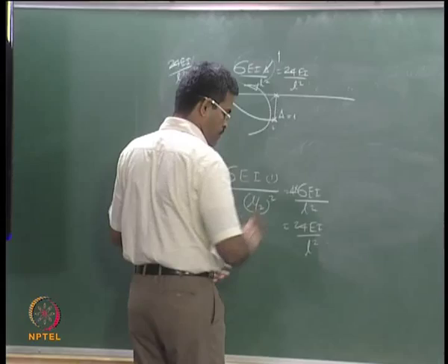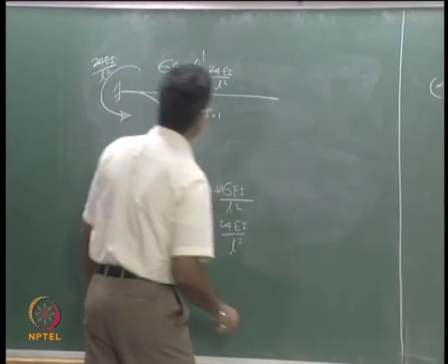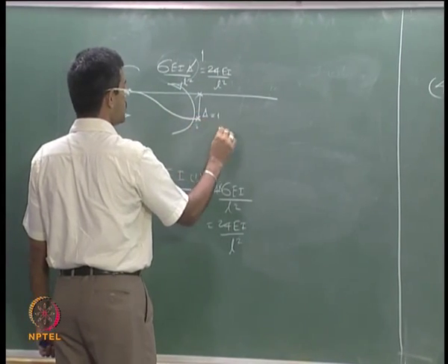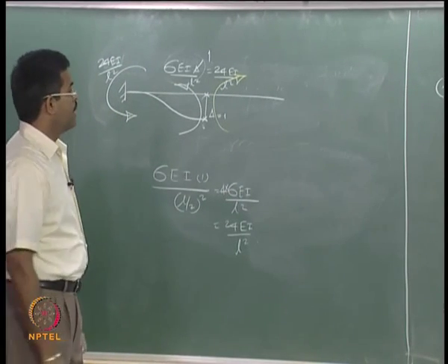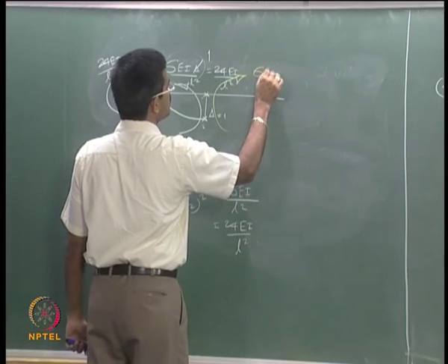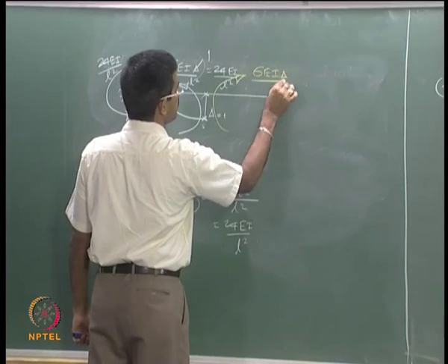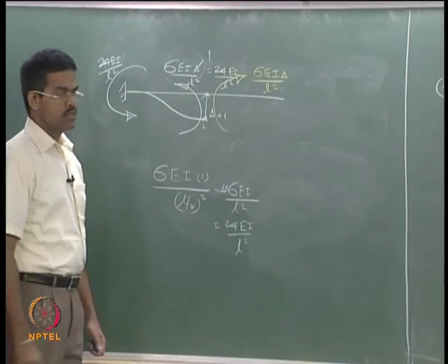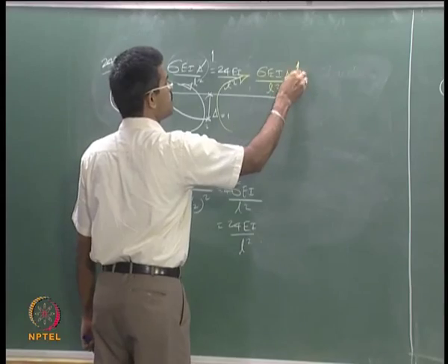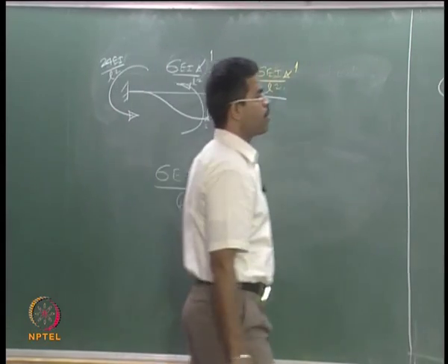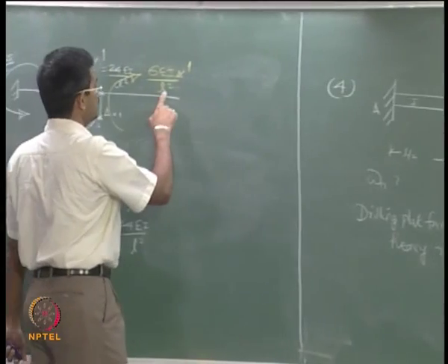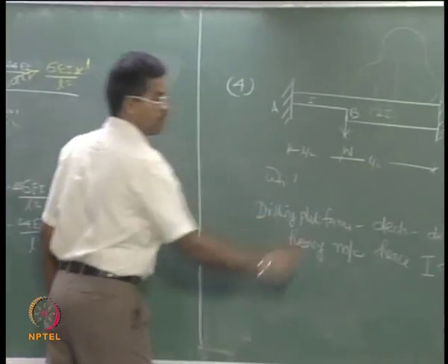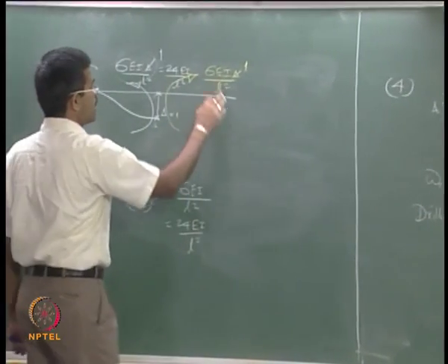Look at the second half of the beam. Now, this is displaced. So, there will be a force applied here, and this will also be equal to 6 EI delta by L square. Delta by definition is again unity, I by definition in the problem is 2I, and L by definition in the problem is L by 2 for my segment. I substitute back again here.